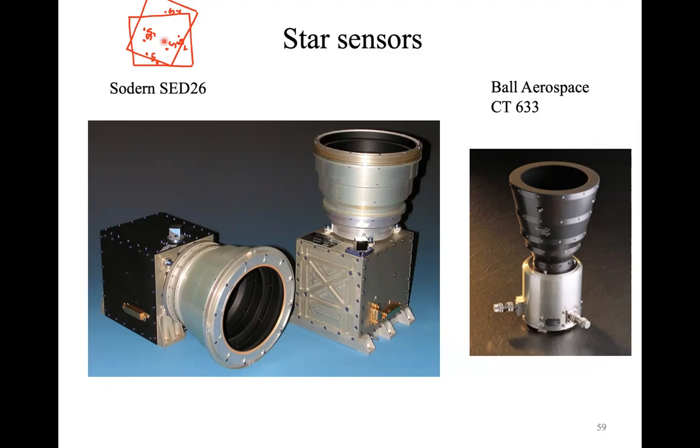So you can substitute your star S2, for example, with an S4. In that case, you are able to still keep the polygon match of the stars, and so you're able to be sure that you are looking exactly at that object. That is an important property. If you have, for example, only two stars, and at a certain time one of the two stars is exiting from the field of view, you can have a possible ambiguity because you have only a single star in your field of view, and that could indeed induce significant errors in your measurements.